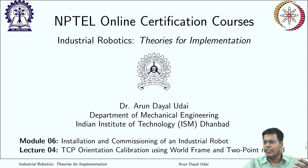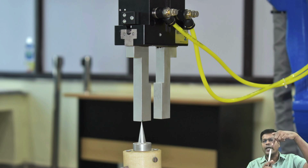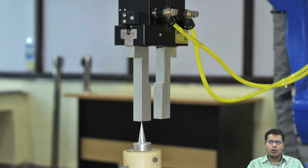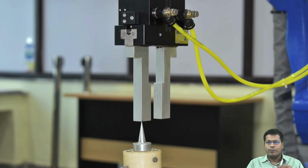I'll just show you the representative image that clearly shows the tip of the tool. One corner I have marked, and you see now I can locate this tool precisely to any reference mark which is there in the workspace of the robot. I can take my robot exactly to that point because that origin is now known. But now I want to orient the robot as well with reference to that TCP origin. So that is what we are going to do today.